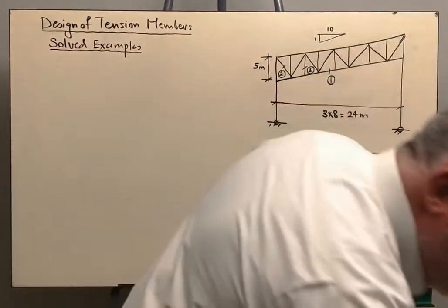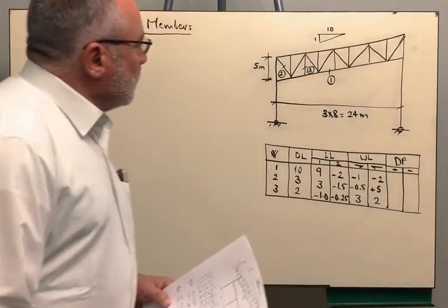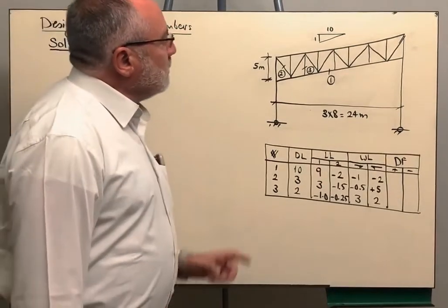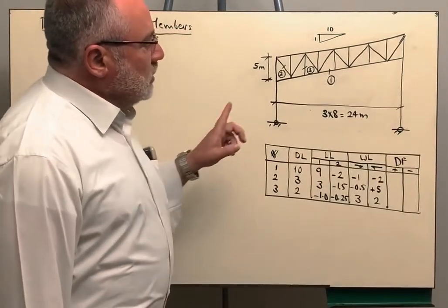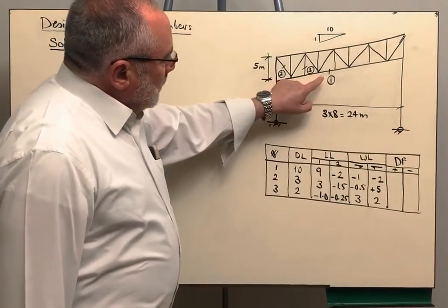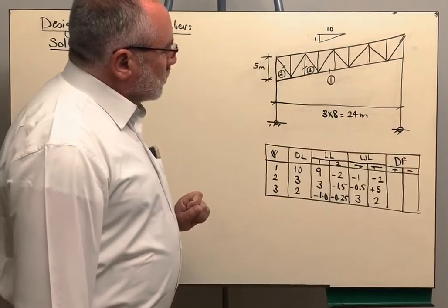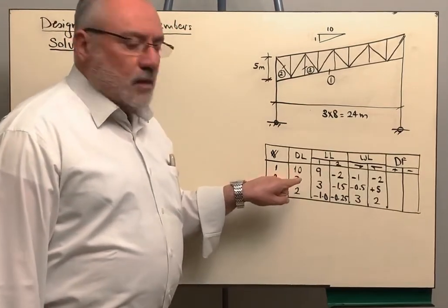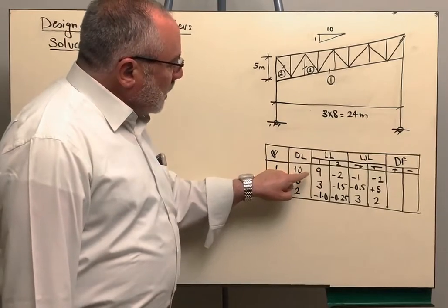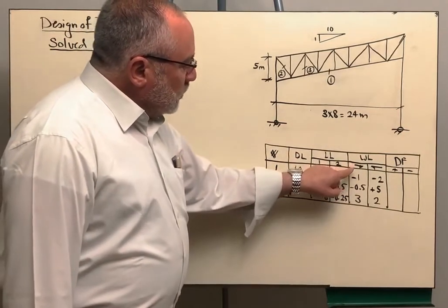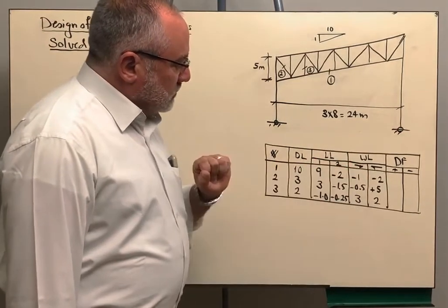Now we have in this problem a given truss as such, where we are having three marked members, similar to your homework assignment exactly. Now we are having member 1. This is a bottom chord member. We obtained the internal forces in this member due to the dead load and due to the live load case 1 and 2 and due to the wind loads left and right.